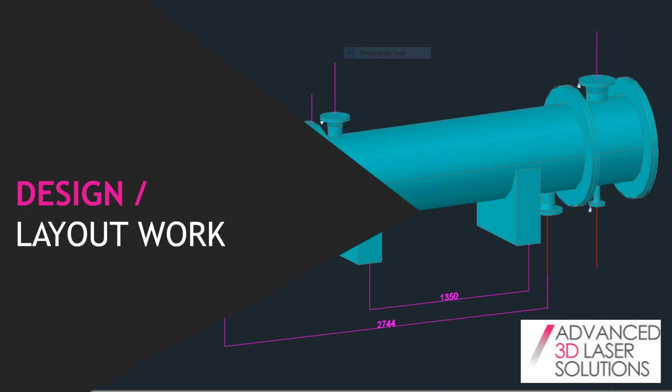The AutoCAD 2D P&ID solution also has this validation check. So everything that you model within your 3D model will also validate against the 2D P&ID. So, for instance, if you've got an 8-inch modelled line with 2 valves on it, and this 2D P&ID is linked to the 3D model, it'll actually check to say, yes, you're right, it has got 2 gate valves in there, and they're meant to be 6-inch, and they're meant to be carbon steel 150 pound. So it's a great checking method to say, yes, that 3D model is exactly what's on the P&ID, and vice versa.